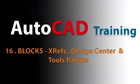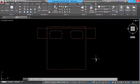In this video, I'll teach you 3 concepts in AutoCAD which are related with blocks. We'll start with external references, then we will see the design center and the tools palette. Using the concept of external references, we can insert different types of files into the current drawing without that file being the part of the current drawing.